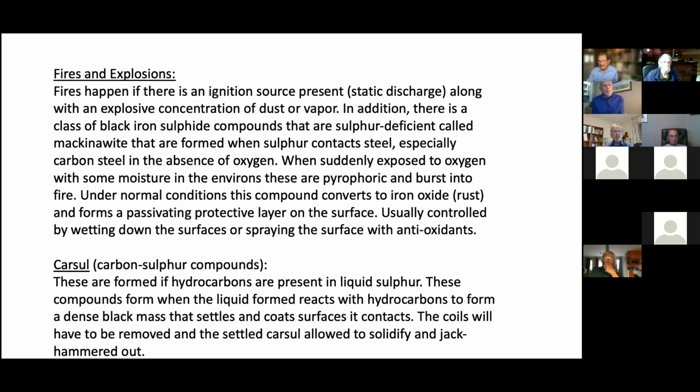And typically in pits, these compounds form, and even in tanks, this happens over a period of time. And that's why you have to shut down to do maintenance on the tank. And when they drain the sulfur, you find a hard, thick black mass at the bottom that you have to jackhammer out, either in pits or in tanks.